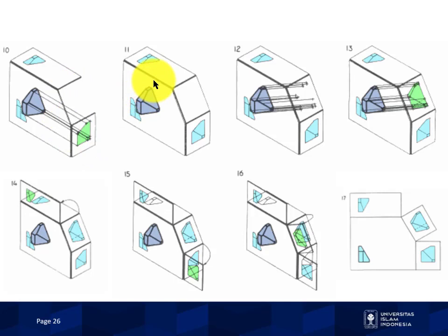And then figure 11, the fourth plane of projection is added parallel to the chosen inclined surface, and perforce perpendicular to the first frontal plane of projection. And then figure 12, projectors emanate parallel from all points of the object perpendicularly from the inclined surface and perforce perpendicularly to the fourth auxiliary plane of projection. Figure 13, an image is created thereby.